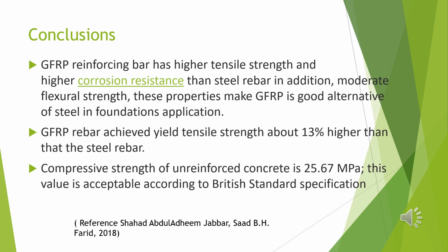GFRP rebar achieved approximately 13 percent higher tensile strength than the steel bar. The composite strength of the reinforced concrete is 25 megapascals, which is acceptable according to the British Standard specification. And finally, it is possible to use the traditional concrete shear design equations for GFRP elements.